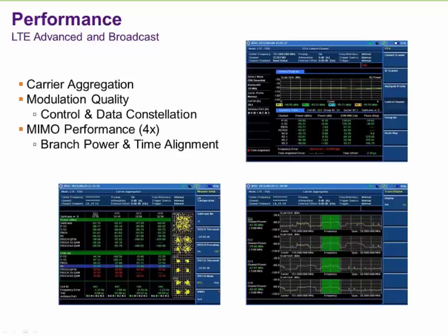In fact, you'll notice on this table, note the reference signal 0. On this second column, this 0 value for reference signal 0. This is the reference that everything else is measured by, and I actually in this classroom had seen an 11 dB difference between RS0 and RS1. I was astounded. First time I'd seen 11 dB difference between the two transmits.